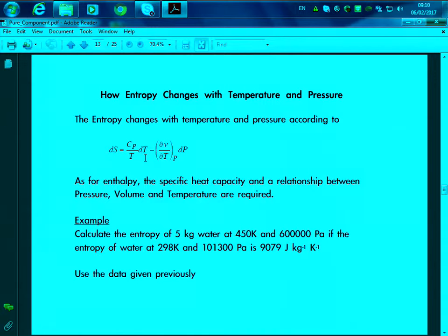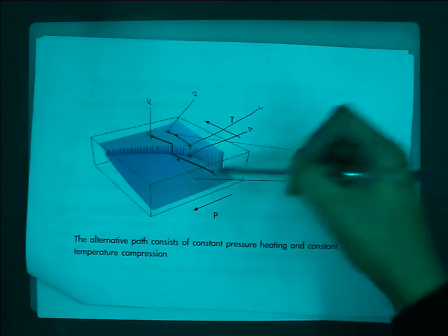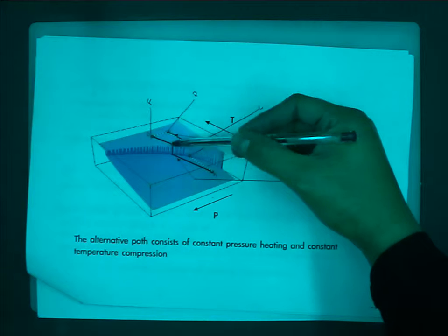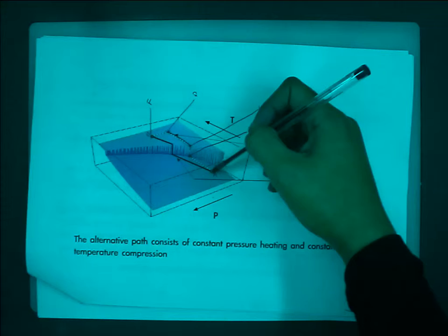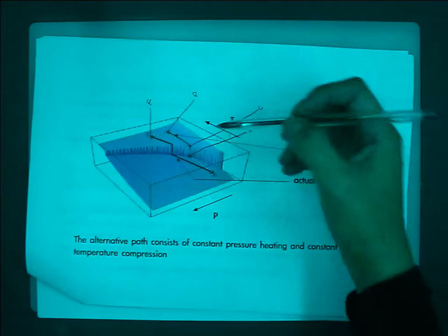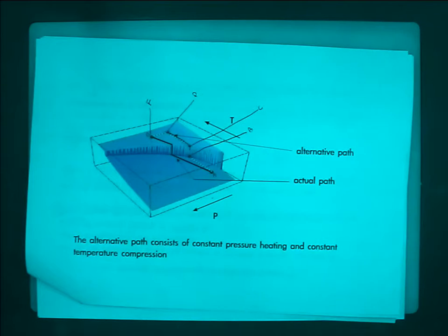on the last lecture. Do you remember how we solved for enthalpy? Just to go back a little bit, the enthalpy curve, that was the process that we wanted to describe. So we were at a pressure and a temperature, and we wanted to arrive at another pressure and temperature. So instead of going through these lines that would imply a change of pressure and temperature at the same time, we basically divided the process into lines that imply constant pressure and a change of temperature, constant pressure and a change of temperature, constant pressure and a change of temperature, and finally a change of pressure at constant temperature. Okay?